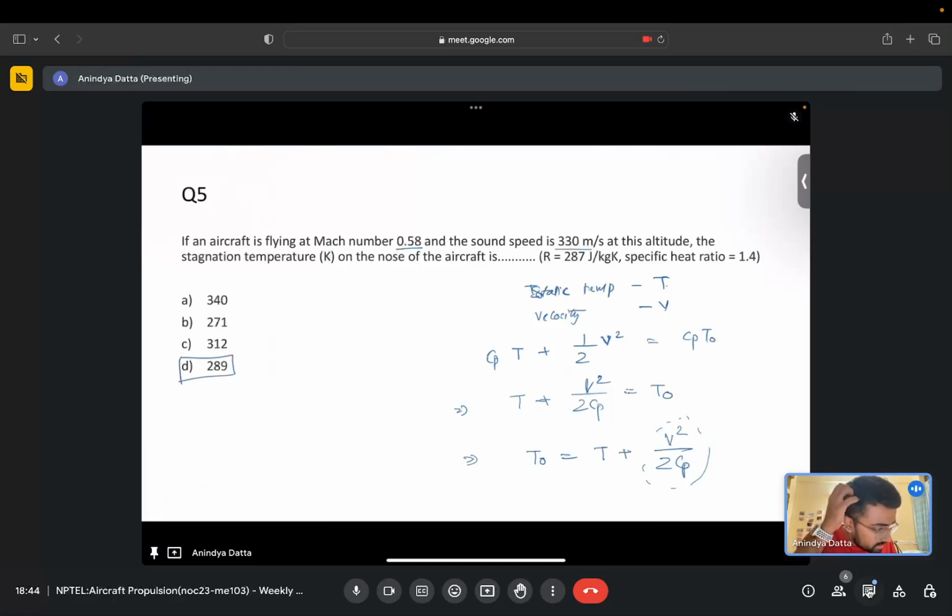Okay, so this is clear. Now the stagnation part is a very important concept. In all the problems of Brayton cycle analysis we have done so far, when we say compressor work input or turbine work output, we just used to do Cp times the temperature difference, right? In that case, one of the assumptions was that the kinetic energy change is negligible. But usually that is not the case.